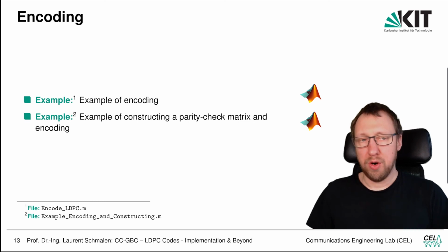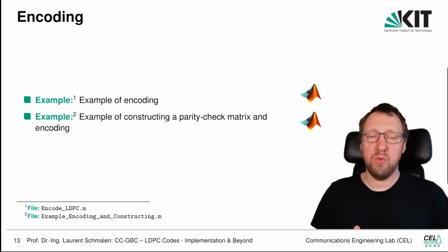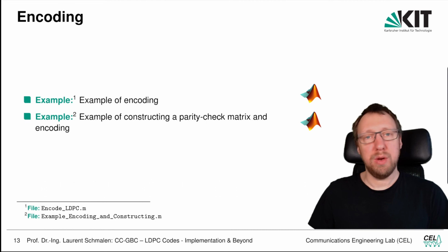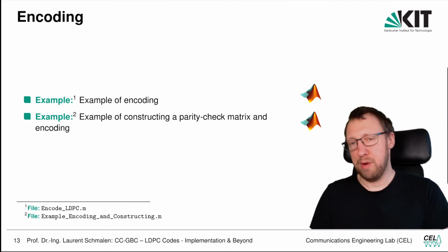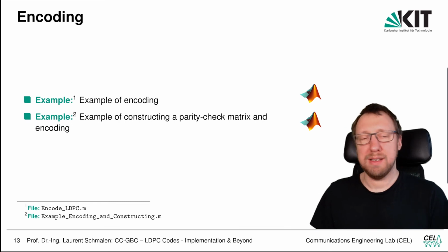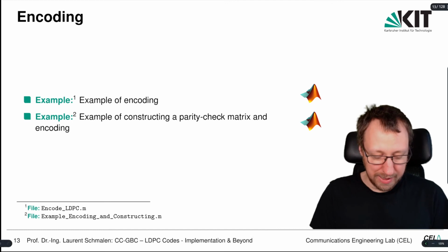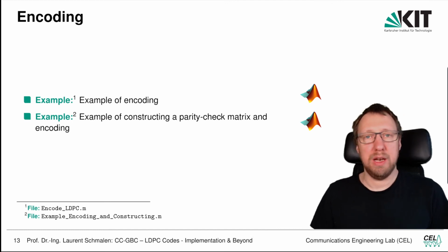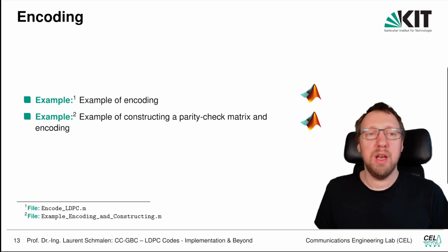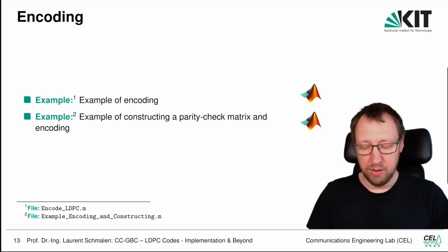There's some word of caution that the encoding we do is not systematic, because that would mean that we would need to reshuffle some of the columns of the original parity check matrix, but that's just a small side note. So essentially the procedure, you have it in the examples, and you can try to construct your own code using what we saw in the last chapter, and then do the encoding using what we saw now here.